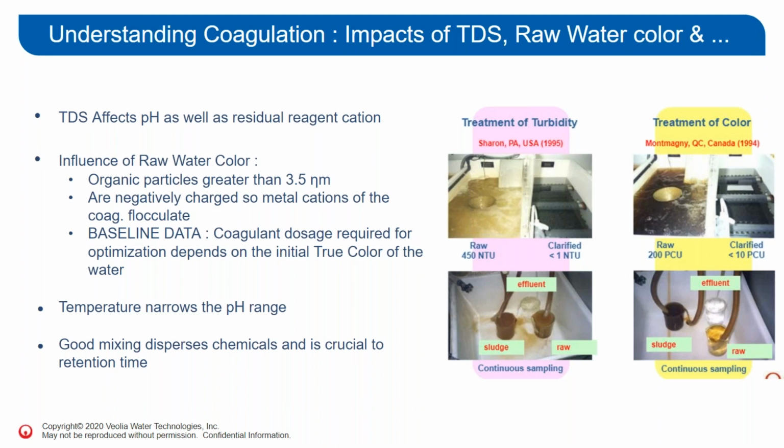So why you need this coagulation, I'm going to just focus on two real sides. You can see this picture on the treatment of turbidity, the raw water separating out to become clarified water and leaving this type of sludge behind. It's whatever suspended particle or soluble particle has been precipitated out.